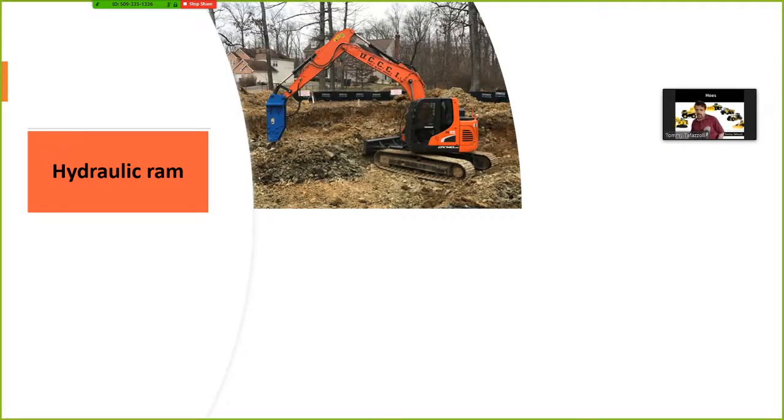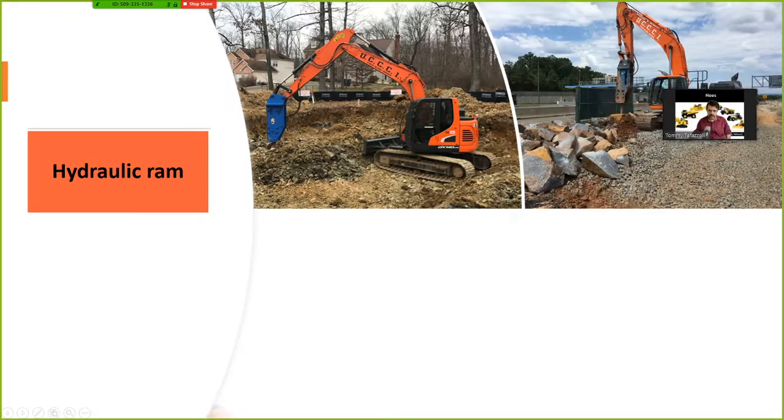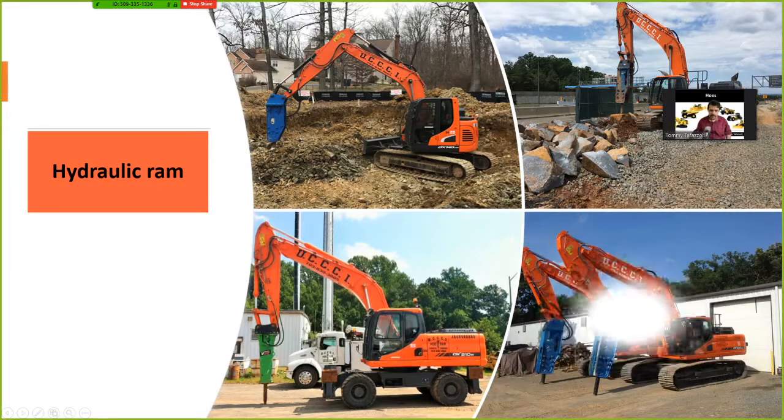Sometimes, instead of a bucket, you could install a hydraulic ram into them. What the hydraulic ram does is that, especially when you're working with hard materials like rocks, it could shatter the materials into smaller pieces, which facilitates excavating them. Okay, and they are super powerful. Once again, the maximum power that they can apply on the earth happens when the stick cylinder is perpendicular to the stick. Okay.